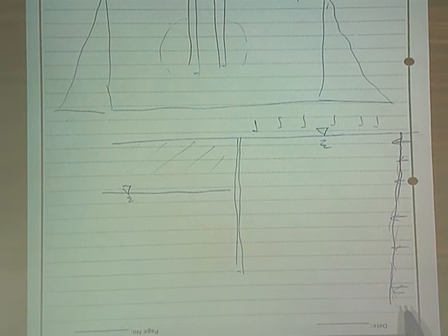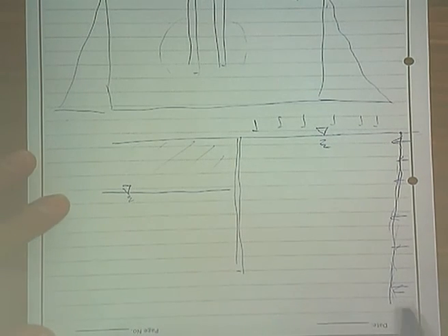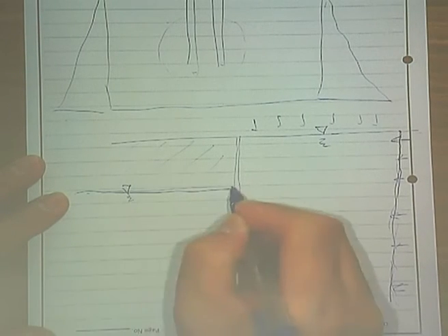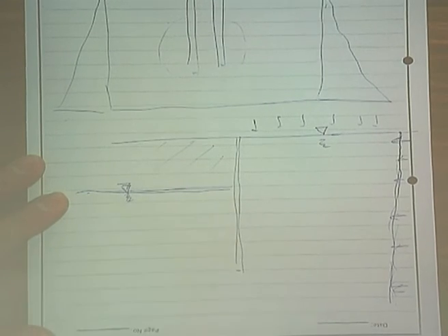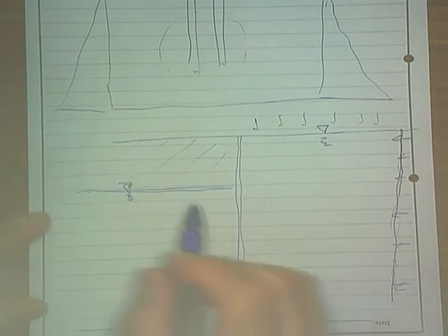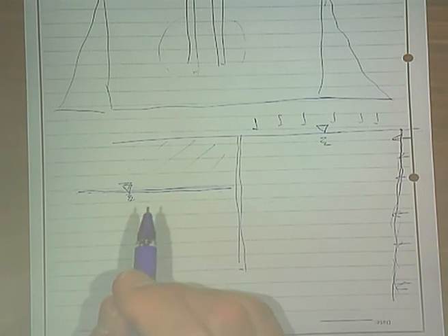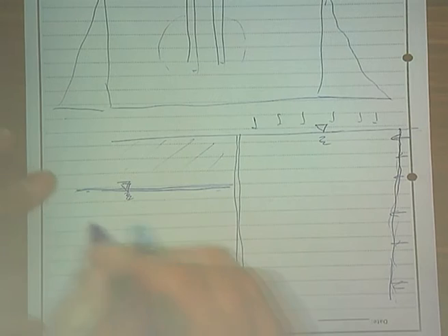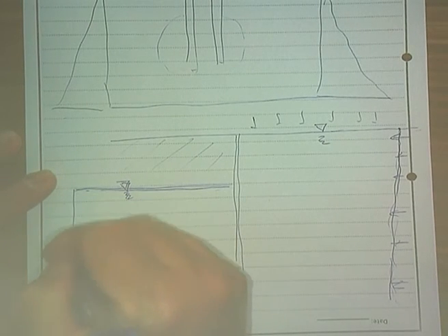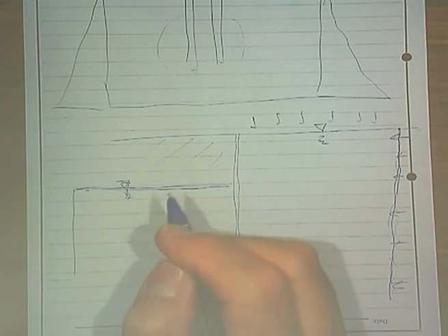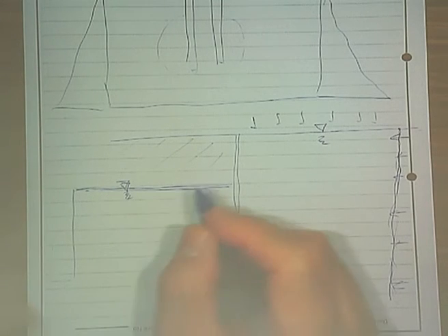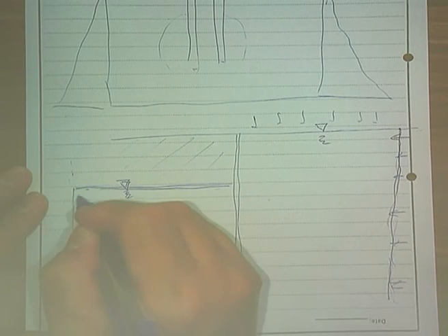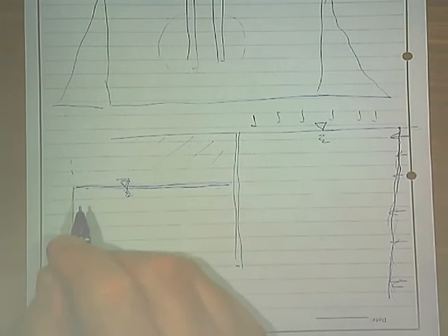Then you have to set this boundary to the new water table, at zero water pressure. Now you may or may not want to set this boundary to hydrostatic, because I don't think it will be hydrostatic. To me, this is more like the center line of the excavation, so there will be no flow going out. If there's no flow going out, you cannot set a pore pressure boundary here.